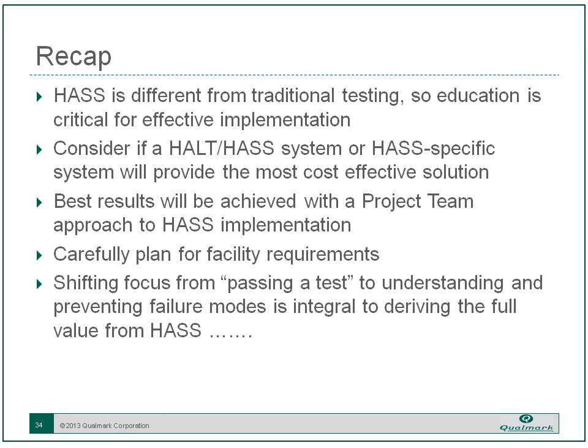So, basically, to give you a recap, HASS is very different from the traditional burn-in or ESS that you're used to doing. So education is important in order to get it effectively implemented. And HASS systems are very different from the typical thermal systems that you're used to installing and using. So a day of education and having somebody you can call to help you out as you go through this process is very important.